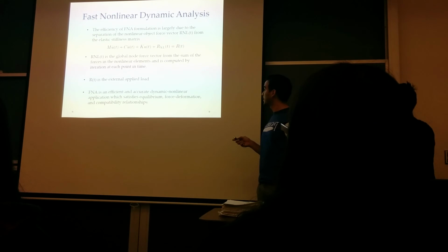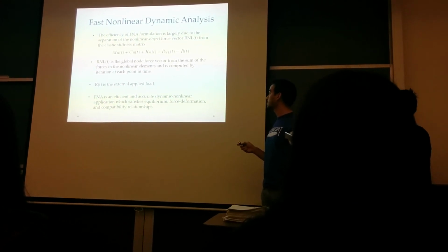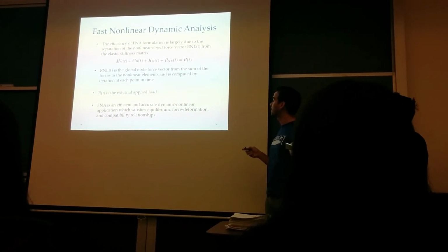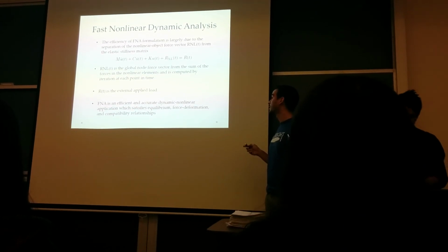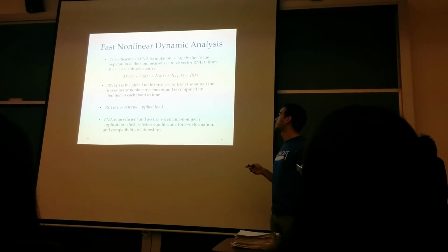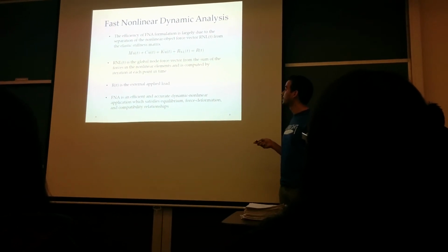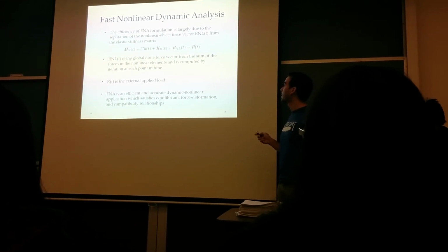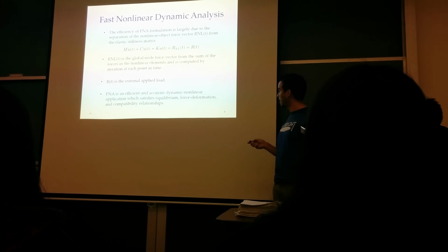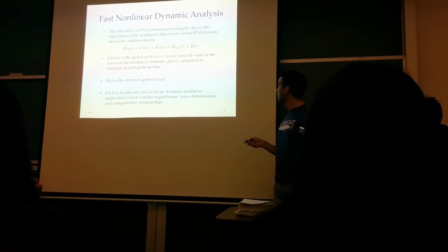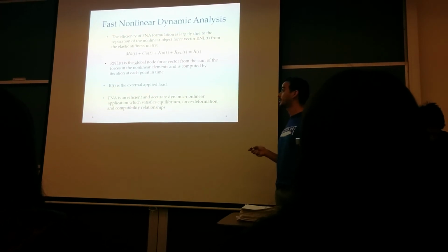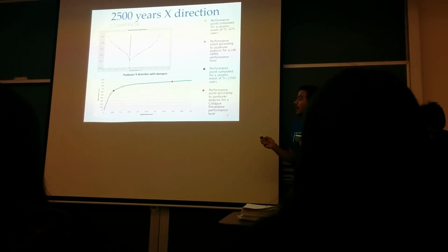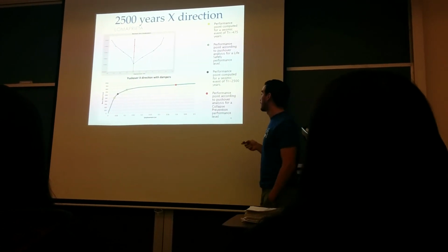This is the equation that the program works with. What it does is separate the elastic K matrix from the nonlinear forces in order to not calculate the K matrix again. This has the ground motions, and the advantage of this method is that it satisfies equilibrium, force deformation, and compatibility relationships. So these are the results that we got.